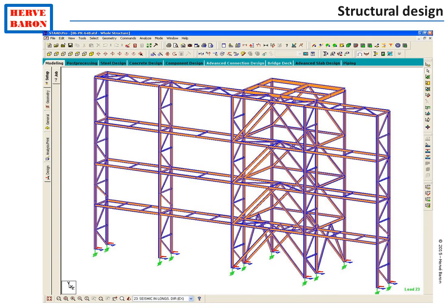The steel structure design is accepted once the stress level in each member is safely below the maximum stress level for the selected grade of steel, and once the maximum horizontal and vertical deflections are not exceeded. Then the calculation note as well as the design drawings can be issued.